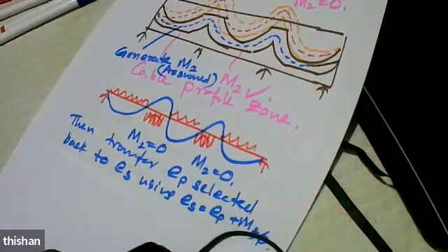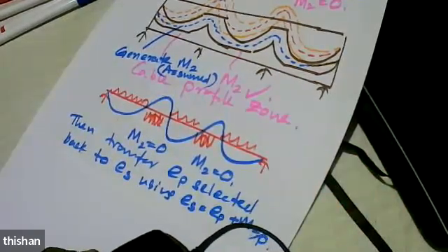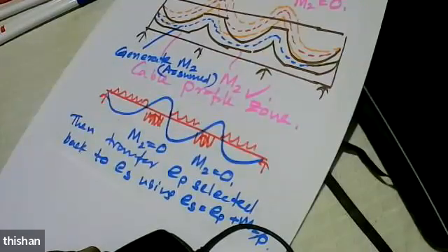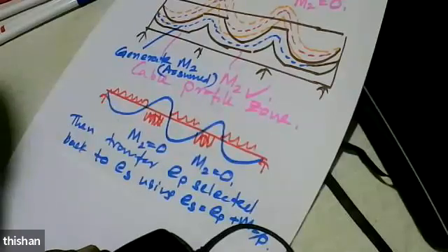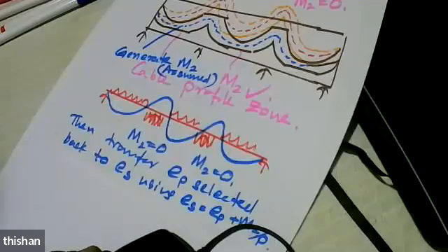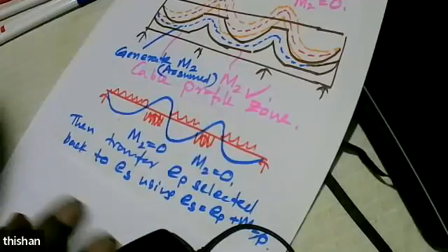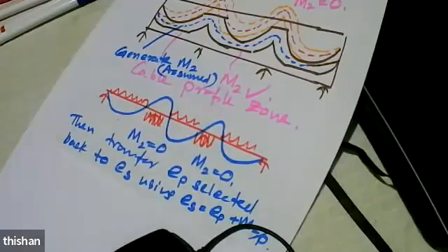And I can show how this method can be used for designing a pre-stressed concrete beam next time using a spreadsheet. And you know, spreadsheet-based calculation is the best for pre-stressed concrete design, because at every section we have to draw a moment diagram. To draw the moment diagram, we need data.